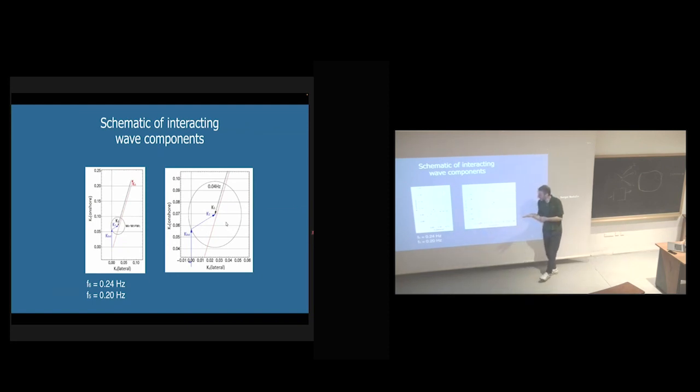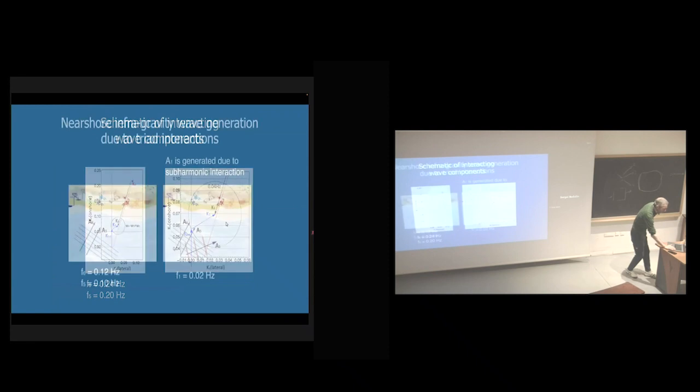And the infragravity wave is generated at an angle to your wave. So your wave is refracting, they are getting straighter to the shore, so they are reducing the spread. But the infragravity part, poof, shoots aside and actually extends the spread. So your infragravity spread, oh, so okay, that's how it will show.